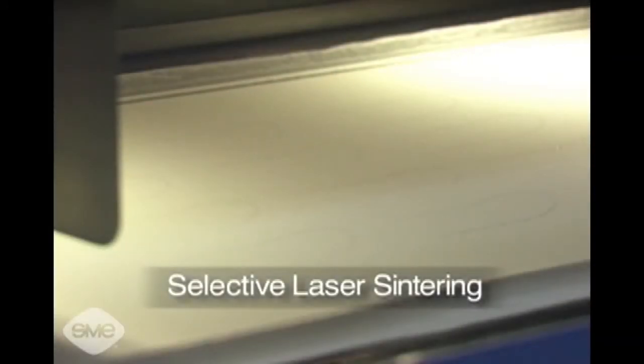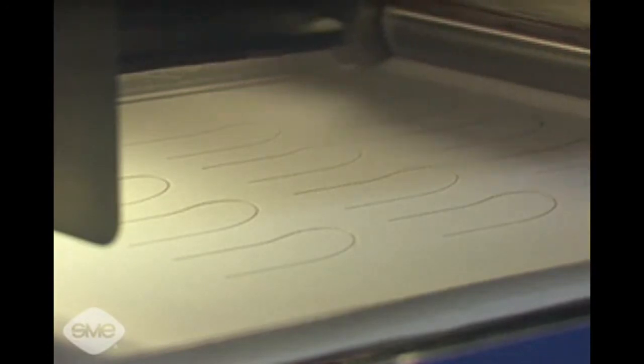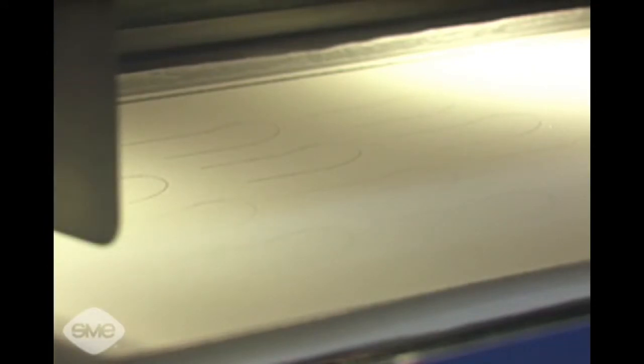Selective laser sintering is somewhat similar to stereolithography, except that the materials used to form models are in powder form, and the laser is a more powerful carbon dioxide unit. A layer of powder is deposited over the machine build area and spread evenly by a roller. Powder layer thickness ranges from 0.003 of an inch to 0.012 of an inch.